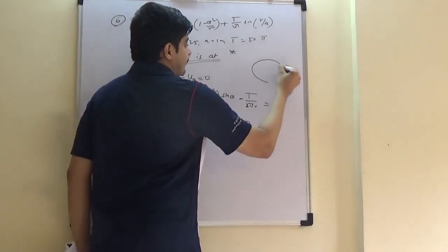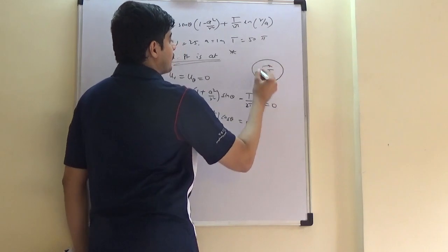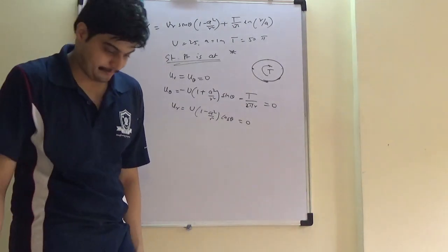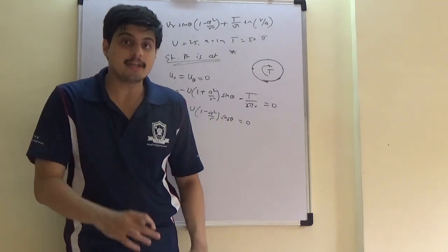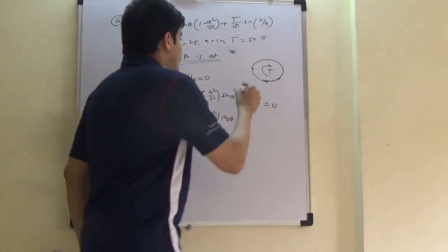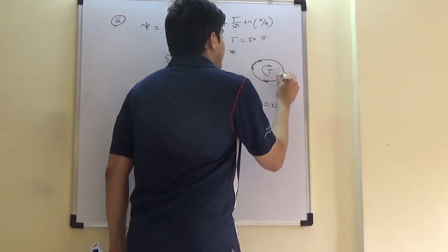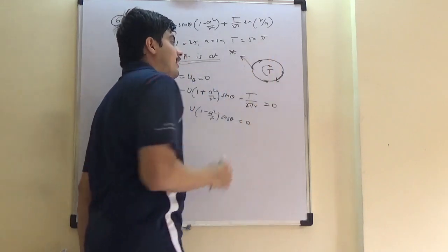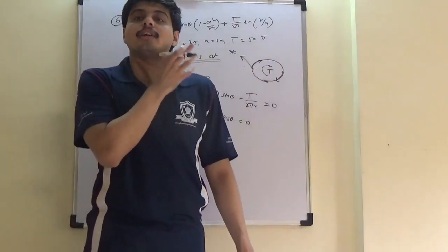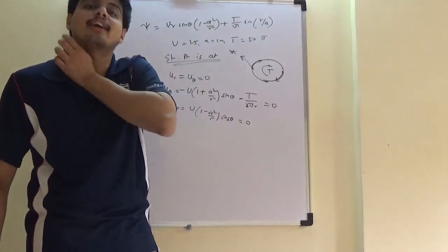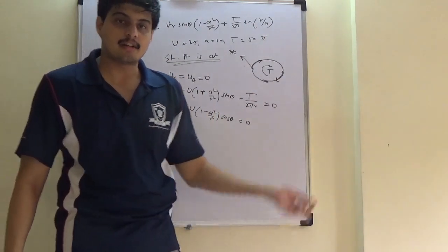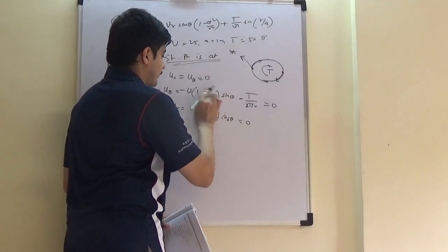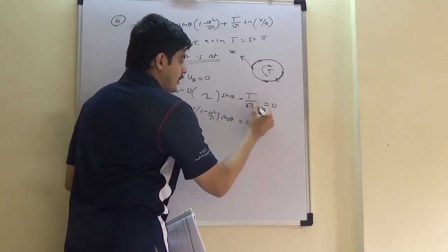Most important, just because you rotated the cylinder, would the stagnation point be on the surface or away from the surface? It has to be on the surface, because rotation just shifts the stagnation point on the surface because of circulation. It does not push it radially, it cannot. It is just a rotational motion, it is not source or sink motion which has radial direction. It is only tangential flow. Tangential flow can disperse things tangentially. So R is equal to A is known.